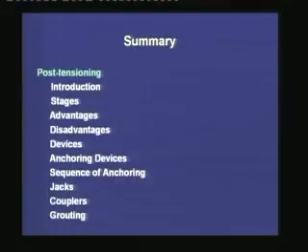The disadvantages of the post tensioning system as compared to pre-tensioning are that for post tensioning we need additional anchorage devices which are much more involved than for pre-tension members, and also we need some grouting equipment for the bonded post tensioning system. Now, transporting this equipment, transporting the jacks, can be difficult if the post tensioning operation is done in a remote site.